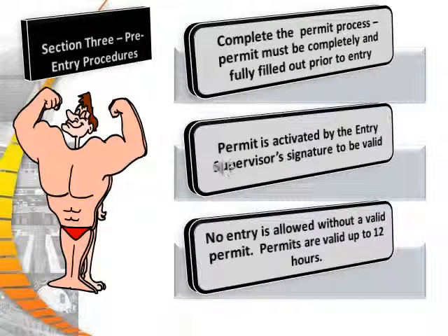Complete the permit process. Permit must be completely and fully filled out prior to entry. The permit is activated by the entry supervisor's signature to be valid. No entry is allowed without a valid permit. Permits are valid up to 12 hours.